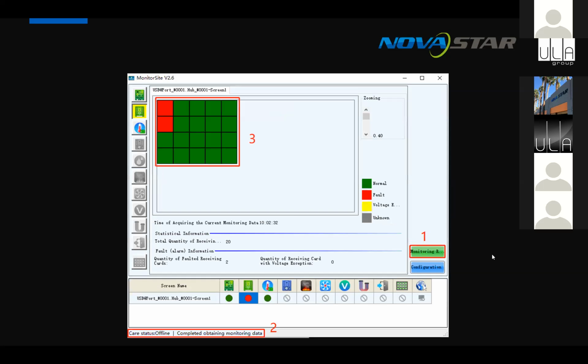The other thing to look at, as I was saying, is that you could occasionally get some false positives. Even though it looks like it's not working, if you refresh a few times, it might come good. But fundamentally, if it does still stay red, then you've got an issue with it, and you just need to go and assess what's going on. Normally, as we said, the issues we had could be a bad receiver card, could be power, could be numerous things.